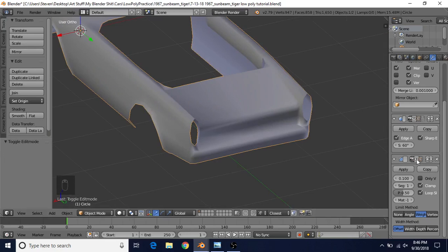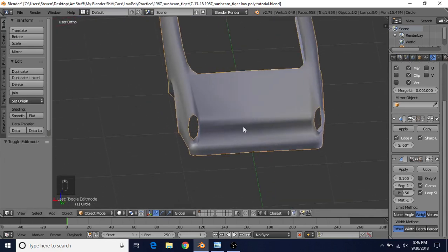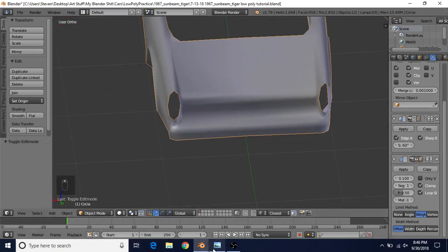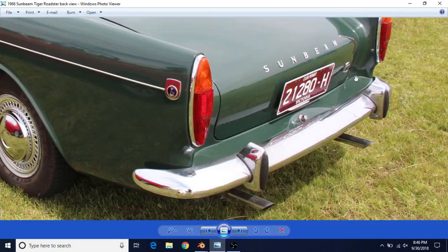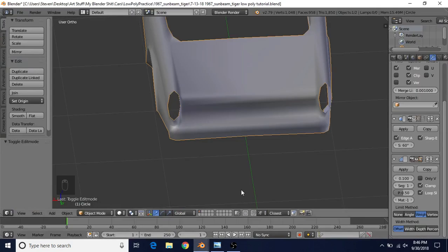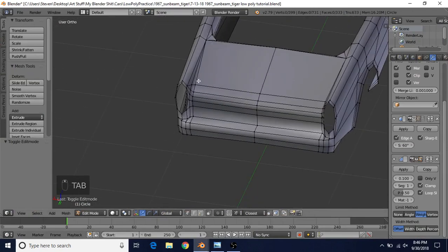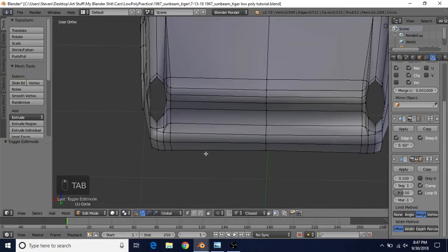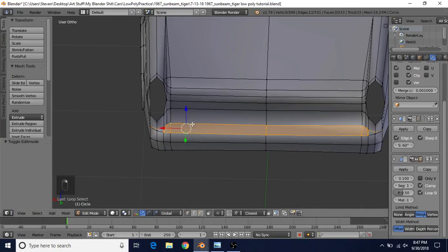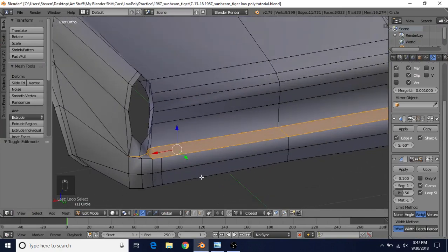Before we save this, we can actually just turn on our bevel modifier again. And another thing we could add if we wanted to is a bevel in this area. You can see this area at the bottom is beveled right here. And then this corner, of course, would be beveled where it's actually bending the metal back downwards. So if we wanted a bevel there, we could do it manually like we did right here. Or you could just Alt right click, Alt and Shift right click.